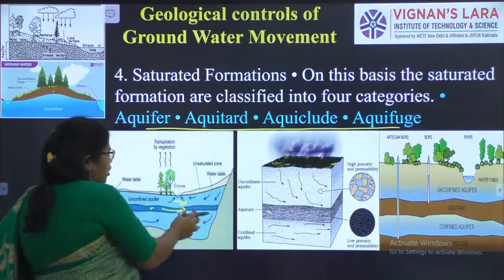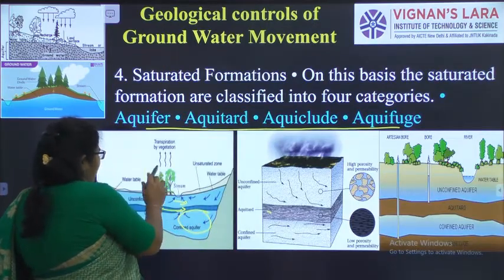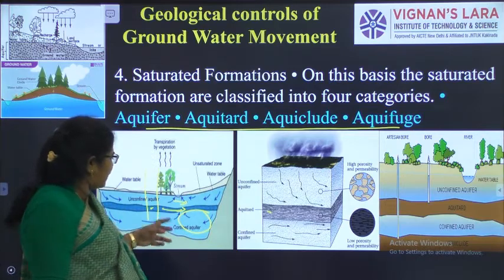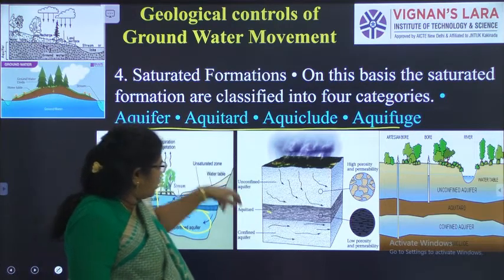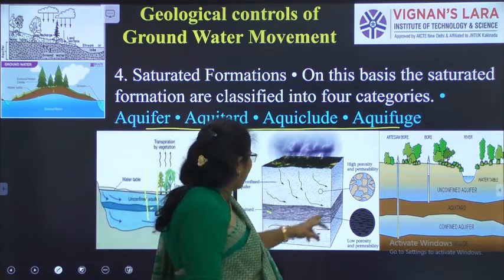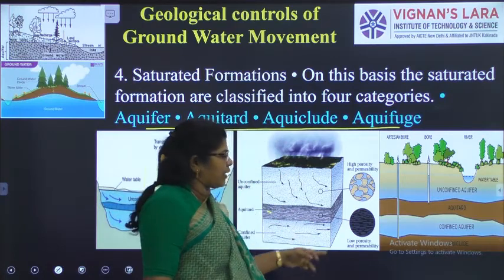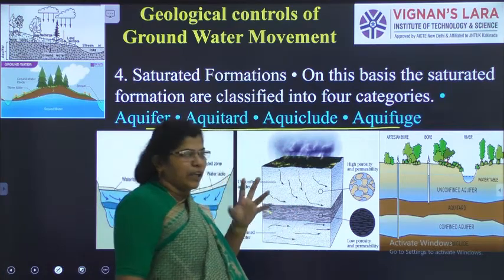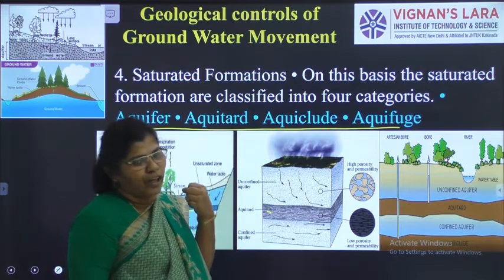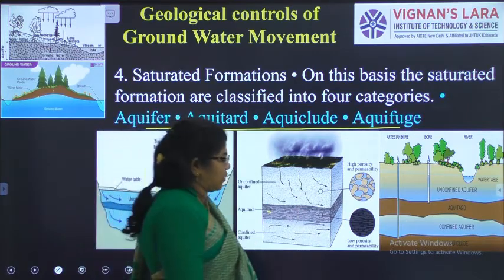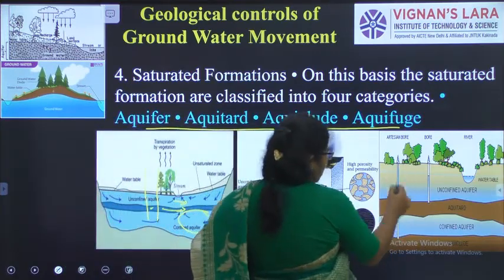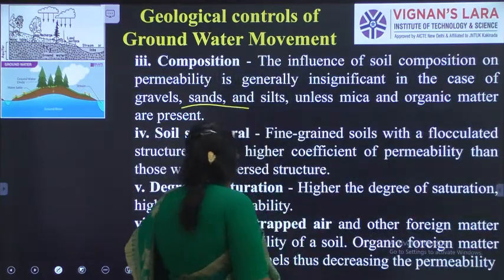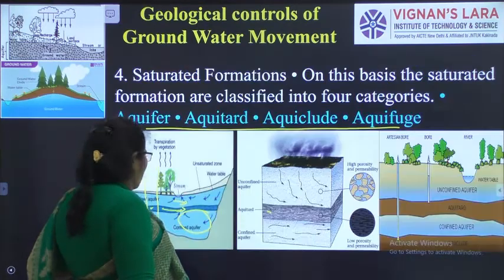Mostly the artesian wells will be like this and get the water out. We can see the movement of water in the confined aquifer and unconfined aquifer, but the aquitard can hold the water and will not allow its movement. The artesian bores go down to the confined aquifer to get the water.